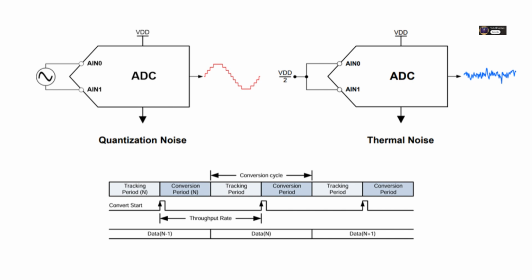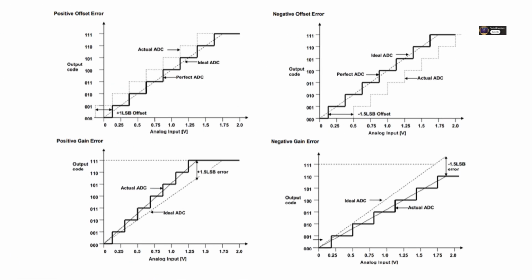Okay. And you mentioned accuracy and noise beyond just the quantization error. What else affects the readings? Right. Real-world ADCs, sadly, aren't perfect. Beyond that inherent quantization error, key error sources include things like thermal noise, just random voltage fluctuations caused by temperature. It adds fuzziness. And then there are systematic errors, like offset error and gain error.